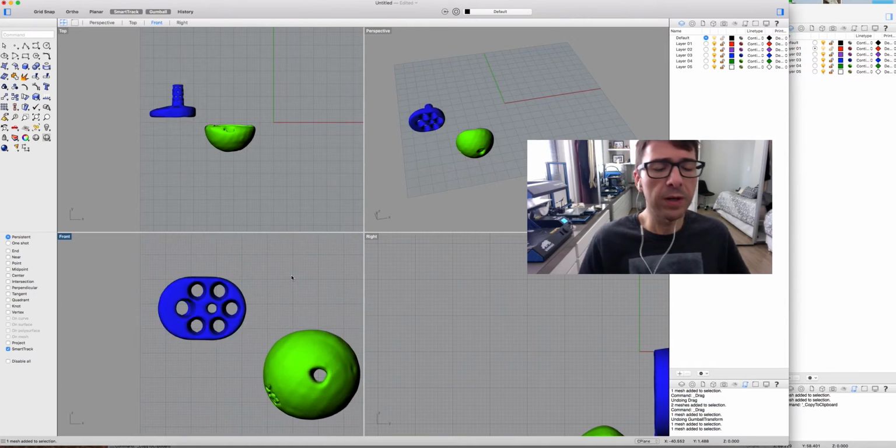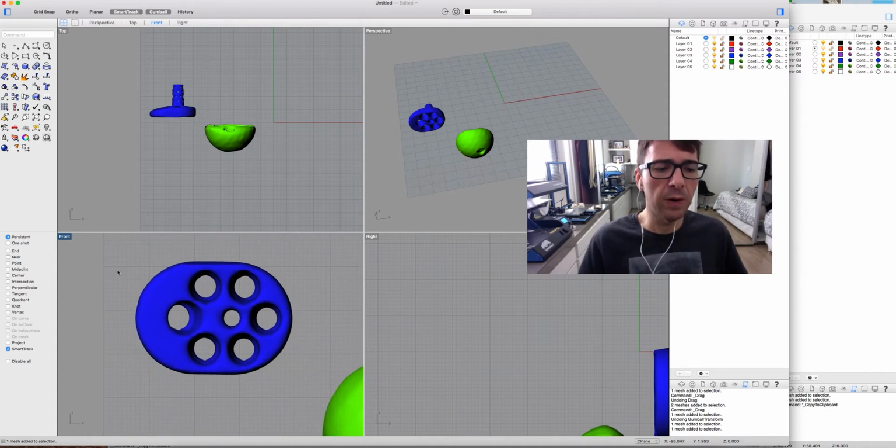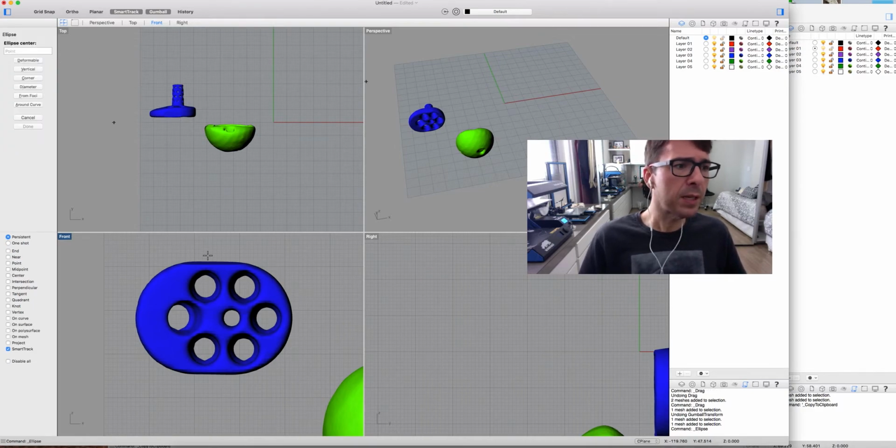We are going to first start on the base plate. As you can see, the base plate is oval. It's not that difficult to design an oval implant, but I'm going to show an easier way where we can create almost any shape. So we're going to click on this right point and click curve. We could do an oval or an ellipse, just like that. We could do an ellipse.